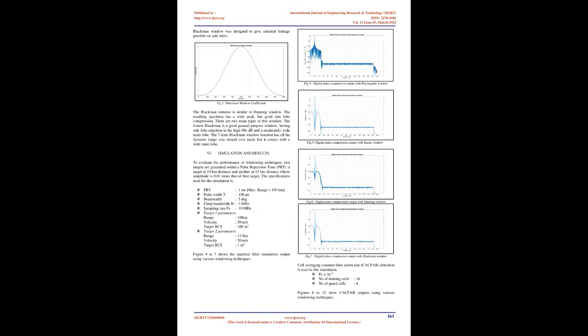If the signal contains strong interfering signals near the frequency of interest, choose a window function with a low maximum side lobe level. If the frequency of interest contains two or more signals very near to each other, spectral resolution is important. In this case, it is best to choose a smoothing window with a very narrow main lobe. If the amplitude accuracy of a single frequency component is more important than the exact location of the component in a given frequency bin, choose a window with a wide main lobe.